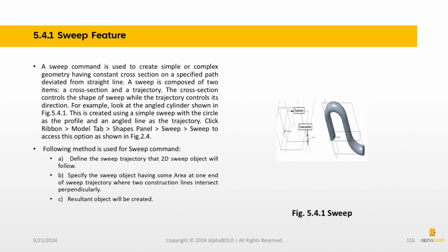A. Specify the section 01 i.e. the beginning of loft profile. B. Specify the section 02 i.e. the end of loft profile. C. Specify offset distance between both sections. D. Repeat step B if there are more than two sections in single lofted object. E. If the vertices of two sections in contact are not the same, make them equal by either dividing the perimeter or any other editing tools.